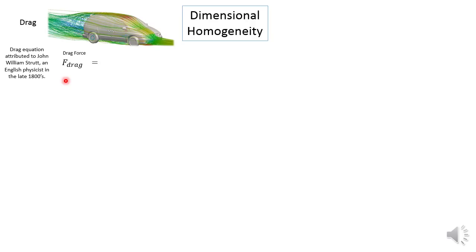He said that drag was a force. If I move my hand through a liquid or a fluid, I feel a force on my hand. He also said that the faster I move my hand through that liquid or fluid, the more force I feel, so it must be a function of velocity. He also said it's a function of density, because if he moves his hand in water, there's a greater drag force that he feels versus moving his hand through air.